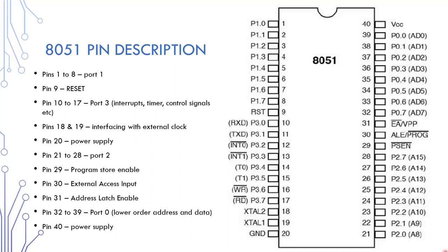Pins 32 to 39 are known as port 0. It serves as an input-output port. Lower order address and data bus signals are multiplexed using this port. Pin 40 is again used for the power supply.